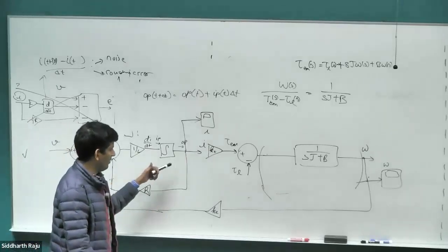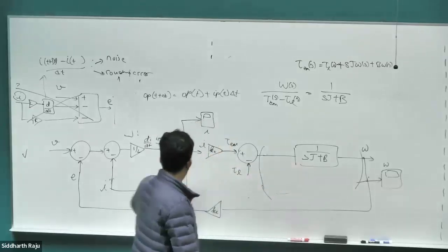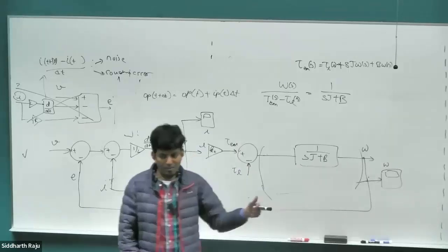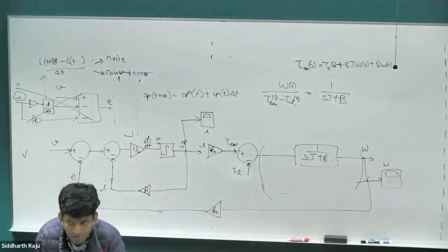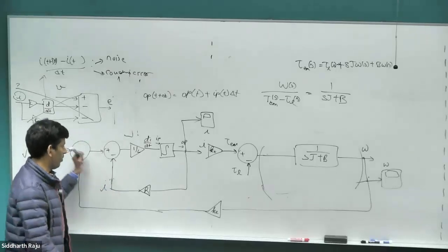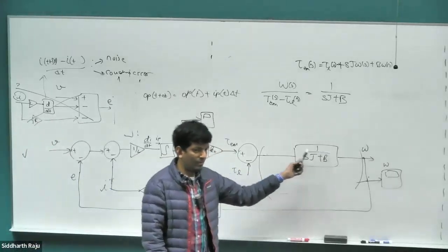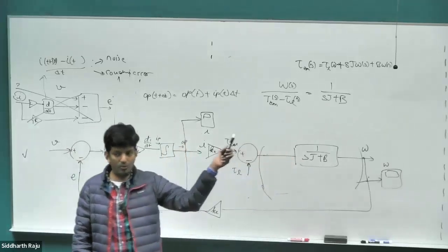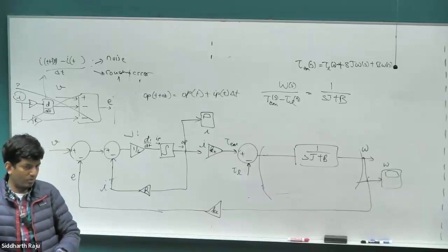So whenever you want to initialize your current to some value, initialize your speed to some value, you would use it in this form. If you don't anticipate any kind of initialization, you would use it in this form. When would you want to initialize? Why would you want to initialize at all? When I start this motor, the current is going to be zero, the speed is going to be zero. So why do I need to initialize? And if I use a transfer function form, it will assume the state starts at zero. That's all good. What would be the reason for initializing it?